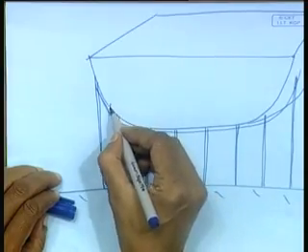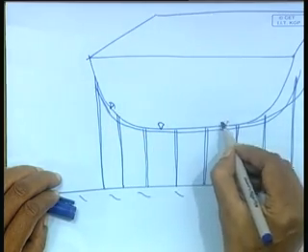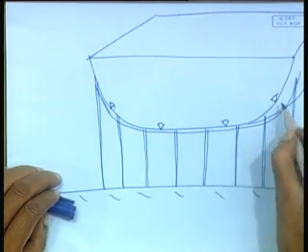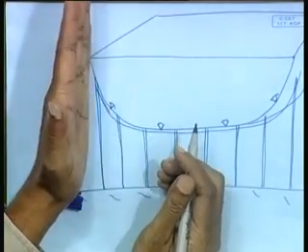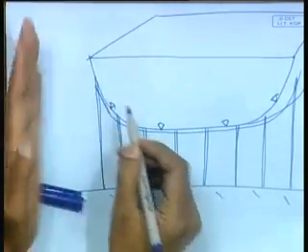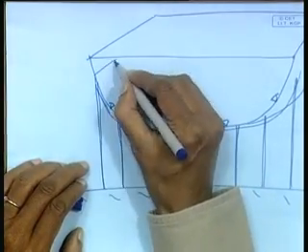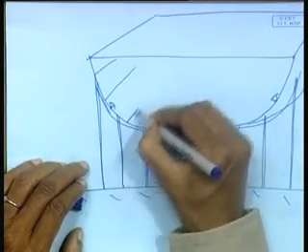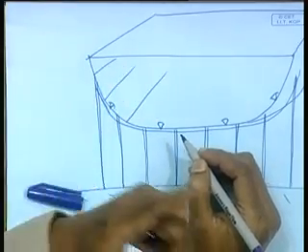Anyway, so what happens as you put the plates, and suppose these two plates are welded here, these are my seam lines. When you weld these two plates, it will try to bend, right. So, such that it does not move, and also when you are welding the stiffeners, it will try to bend.